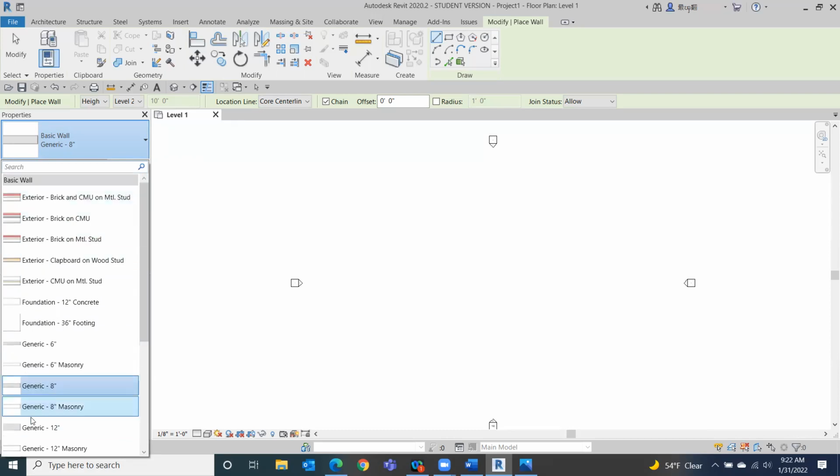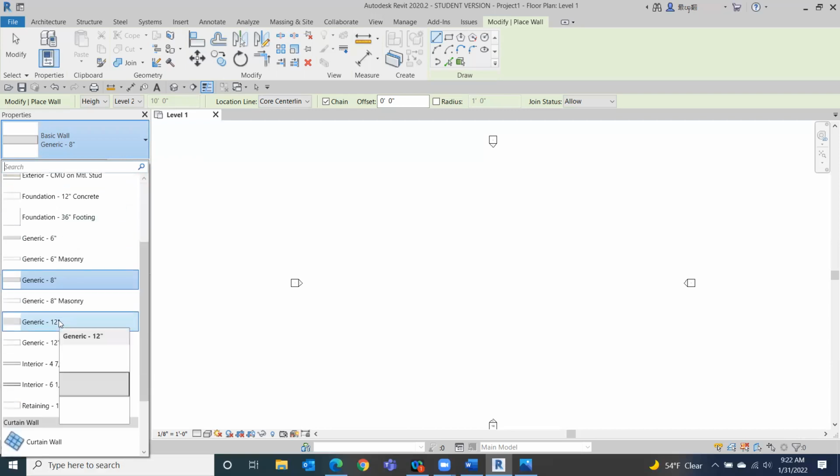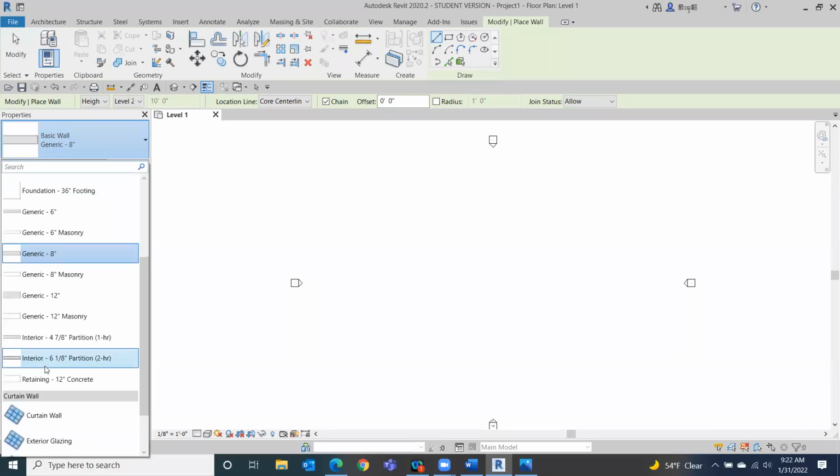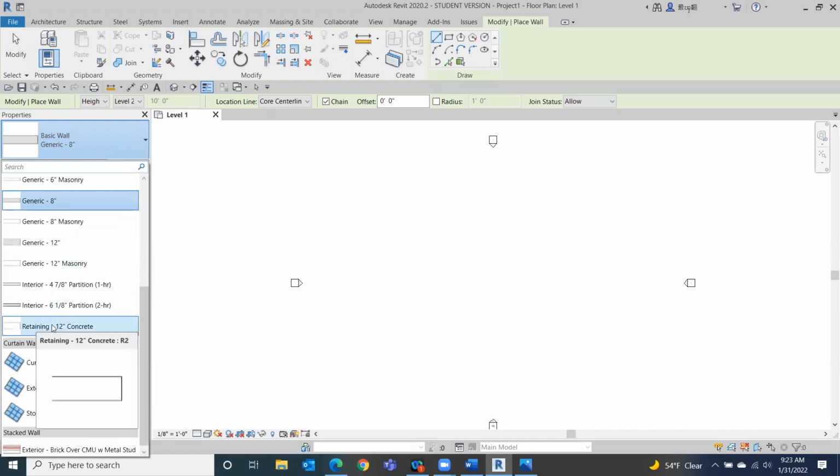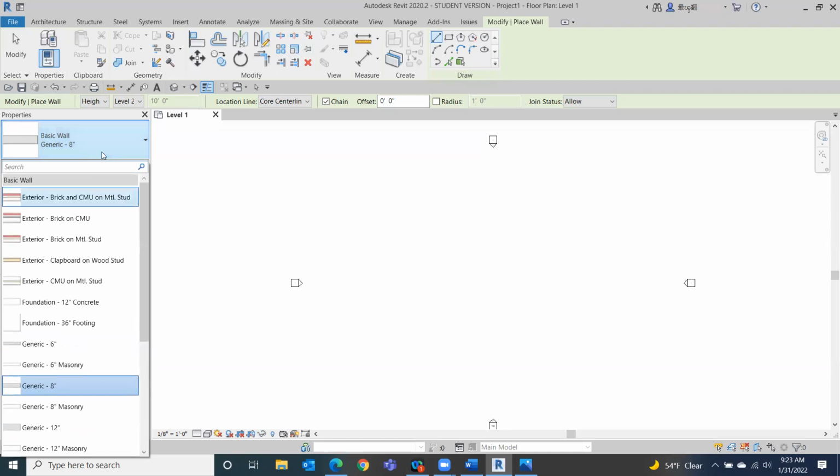Notice everything is alphabetical, E's, F's, G's. The reason I draw that to your attention is that when we create our walls, it's sometimes easier to keep everything grouped together so we're not having to hunt through and look for stuff. So what I typically do in my naming nomenclature is I'll start all of my stuff with wall, obviously, because I'm creating a wall. That way I just know I have to go to wall and then find the other information for it. But think about how you're naming stuff, and it just makes things easier for you to find it later on.